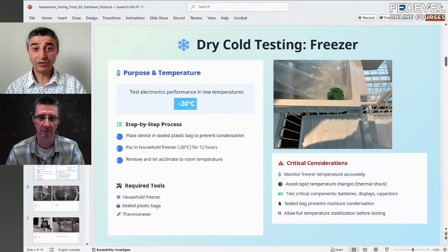If you go to the industrial, where systems need to have an MTBF, or mean time between failure, of more than 10 years, you have a very low failure rate. This is not the mindset. That's why we have IEC standards, mil standards to govern how things are brought into the space. Like I said, it's consumer mainly, but there are good companies, there are okay companies. So the lesson is, please do use your freezer, make good testing, and find out the root causes and issues right away and fix them.